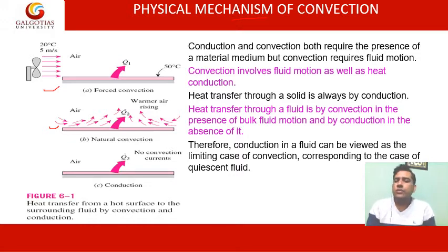Heat transfer through a solid is always by conduction. Heat transfer through a fluid is by convection in the presence of bulk fluid motion, and by conduction in the absence of it. So if there is no fluid motion, then the heat transfer is through conduction only. But when fluid motion is present, the heat transfer is called convection. Therefore, conduction in a fluid can be viewed as the limiting case of convection, corresponding to the case of quiescent fluid.